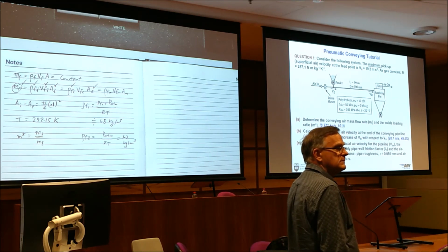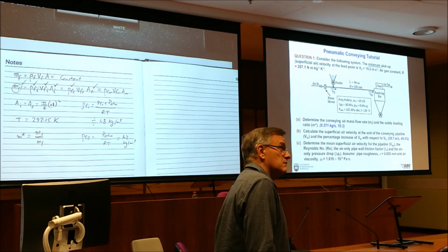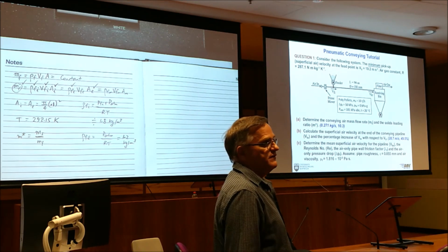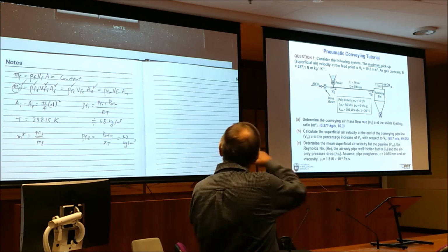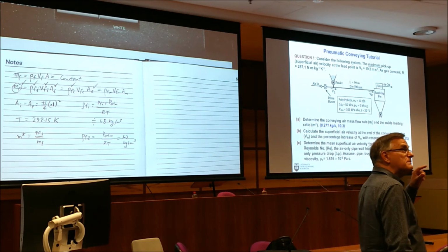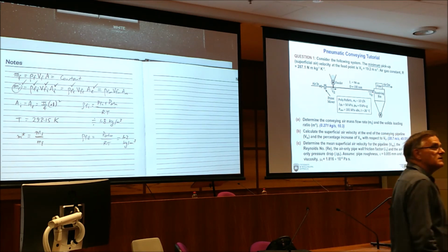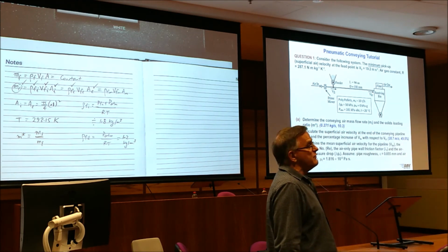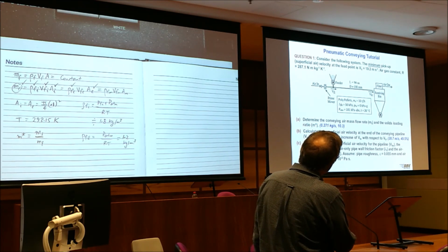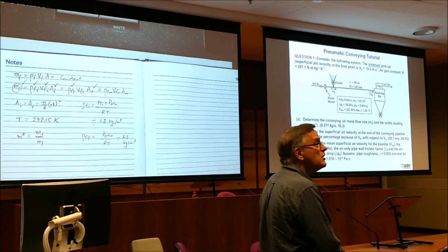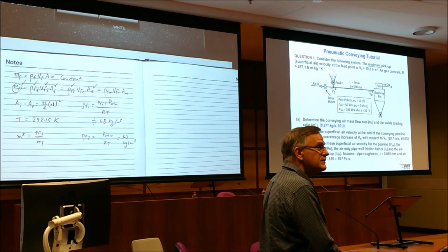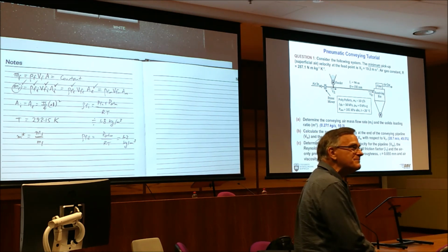Now you could do it the other way. You start off with VFM equals VFI plus VFE over 2, and then you go back to continuity to calculate rho FM, but that logically doesn't make sense because you talk about a mean pressure of a system. And we can actually do that very quickly because you have to understand, the gauge pressure there is 50. The gauge pressure there is 0. What's the average pressure? 25. The absolute average is 126. You can work out rho FM immediately.